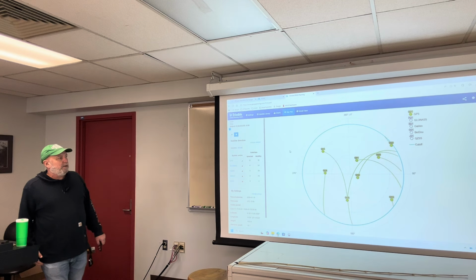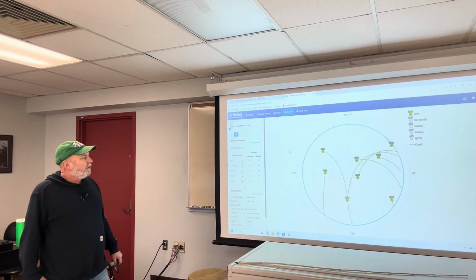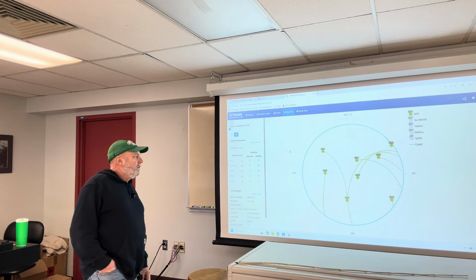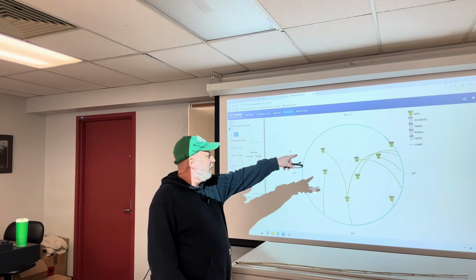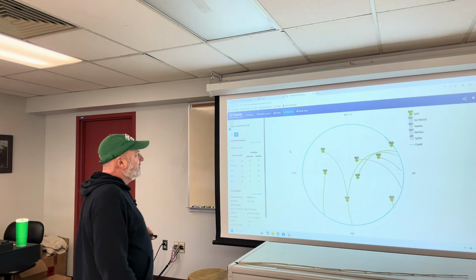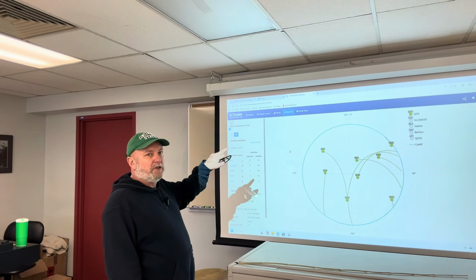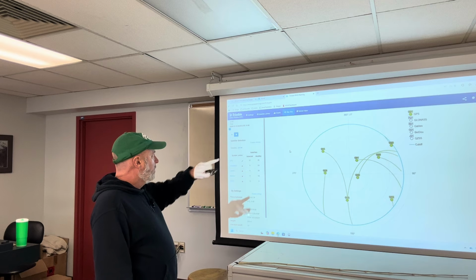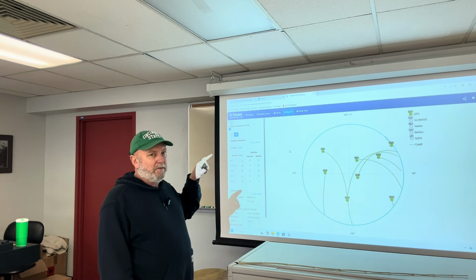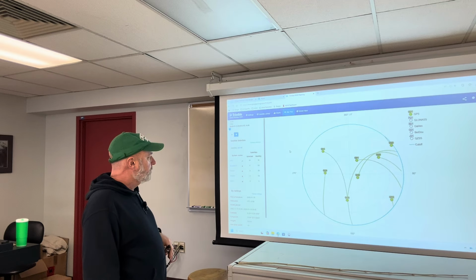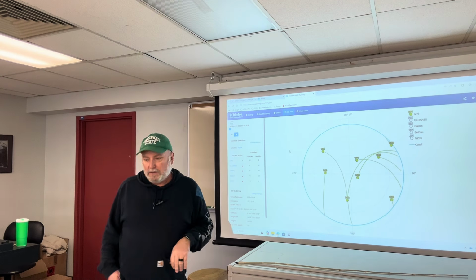So here's the general sky plot. You are at the center. These are how the satellites actually look overhead. Like your G29 up there in the top right, that might be a little questionable because you're getting close to that elevation mask, which is shown here by the light blue line. The faint circle all the way around, that would be 0. That's your horizon. That looks like pretty good geometry right there.